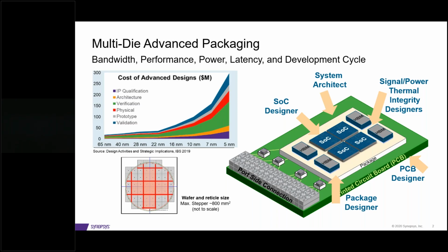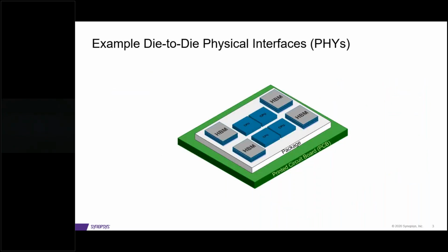Similarly, where you put your C4 bumps or the copper pillar bumps with respect to the other devices determines how well you can get the most optimal package substrate design, where these structures are connected to the package substrate, to get the best escape routes to minimize the number of package substrate layers for the most optimal pricing and also better performance.